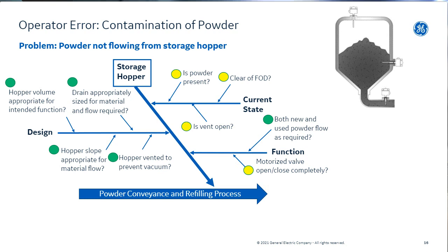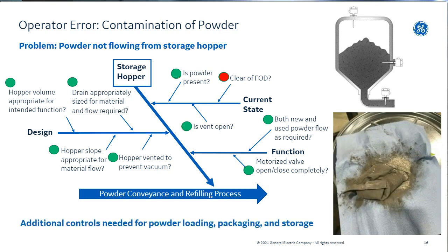And very quickly, we found there was something else in there, and it was a desiccant bag. This is what the powder is often shipped with to keep it dry from humidity during shipping and things like that. It happened in an unfortunate way, not finding the bag entirely intact, sticking a tool up through the bottom of the hopper to poke around and see, is there some kind of obstruction? And these little white, clear silica gel packet things started pouring out. And then some powder came out, and then we closed the valve and opened the top and found there was some desiccant bag in there.